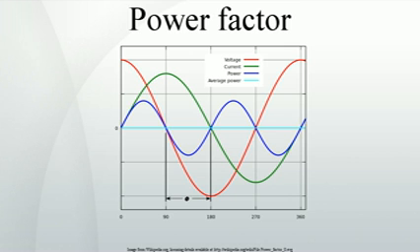Active PFC. An active power factor corrector, active PFC, is a power electronic system that changes the shape of current drawn by a load to improve the power factor. The purpose is to make the load circuitry that is power factor corrected appear purely resistive, apparent power equal to real power. In this case, the voltage and current are in phase and the reactive power consumption is zero. This enables the most efficient delivery of electrical power from the power company to the consumer. Some types of active PFC are boost, buck, and buck-boost. Active power factor correctors can be single-stage or multi-stage.